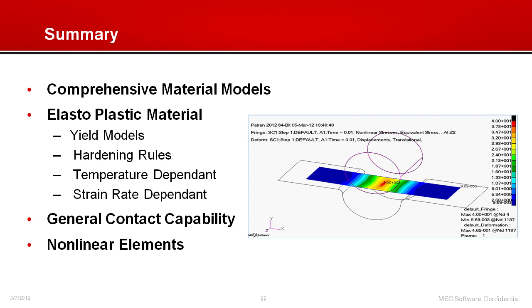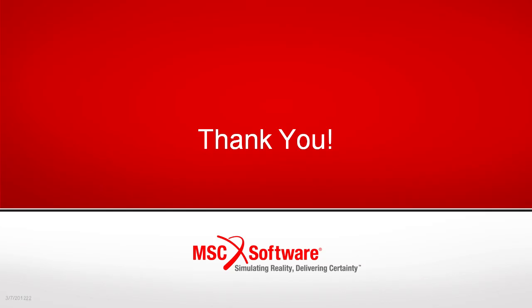During the demo, I mentioned the contact capabilities available in the nonlinear solution sequence in Nastran, both deformable bodies and rigid bodies for the die and punch. And finally, to do a nonlinear simulation with nonlinear materials, we need to have nonlinear elements to capture the plastic strains. We are talking about plastic strain greater than 5%, and we need nonlinear element formulation inside Nastran, which is also available as part of the nonlinear solution sequence. That concludes my presentation today, and I will transfer the control back to Srinivas at this time.